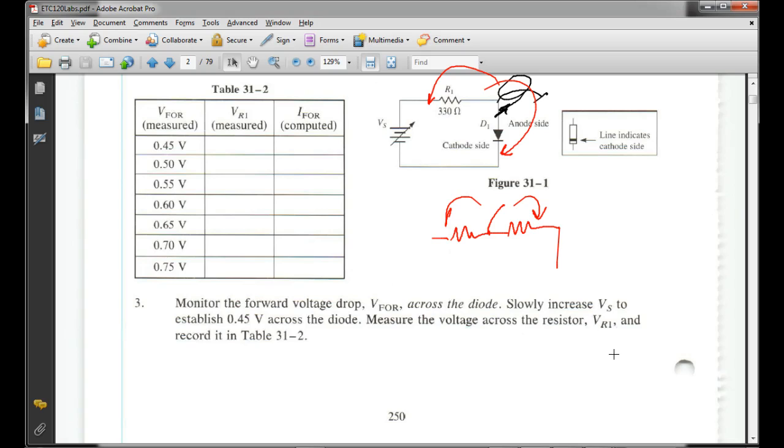But the other probe, you have to put at the same location. So a good way to check is to take your probe and click it in there. If you see a signal, then that means those are referenced to what? Ground. If you get garbage, it usually means it's not referenced to ground. But with meters, we can put that black lead on our meter any way we want to. So we okay? Yes? Okay.